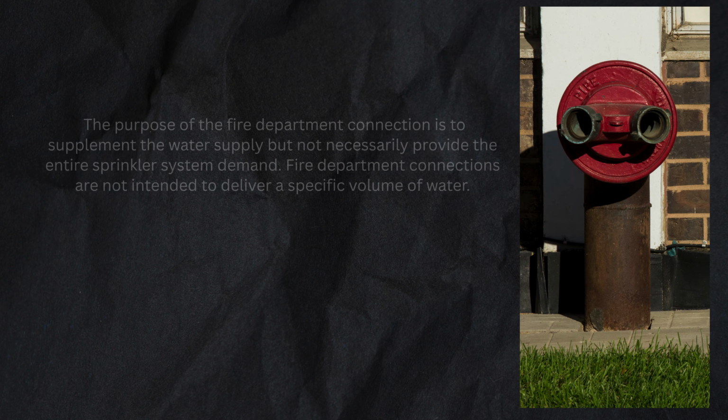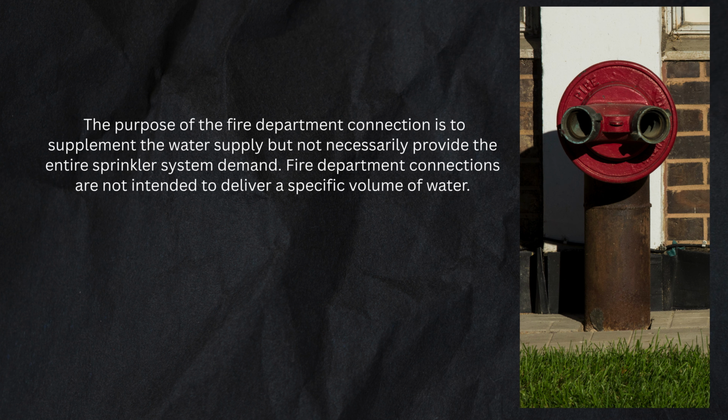Fire department connection: a connection through which the fire department can pump supplemental water into the sprinkler system, standpipe, or other water-based fire protection systems, furnishing water for fire extinguishment to supplement existing water supplies. The purpose of the fire department connection is to supplement the water supply but not necessarily provide the entire sprinkler system demand. Fire department connections are not intended to deliver a specific volume of water.